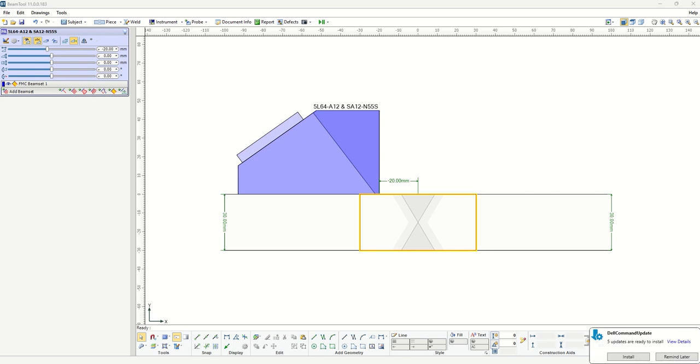In previous videos, we introduced the concept of point spread function and showed you examples of how it can be a powerful tool for designing full matrix capture inspection techniques, and how we used quality maps that we get from point spread function simulation to assess the quality of the inspection technique we design for full matrix capture. In this video, we want to show you that those quality maps can also be used when we are designing a phase array inspection technique.